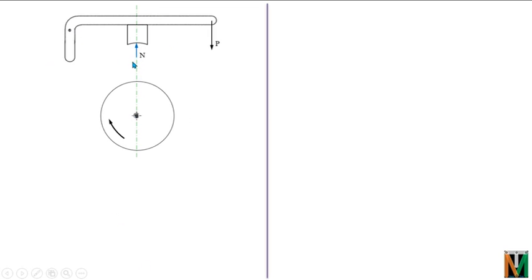So this is the central line of the block and the drum. This is the normal reaction of the drum on the block. This is the radial force applied by the block on the drum. Similarly, we have the frictional force. This is the friction force on the drum as we have seen earlier, and this is the friction force on the block. These will be equal to mu into N. Now the distances are again A and L minus A.